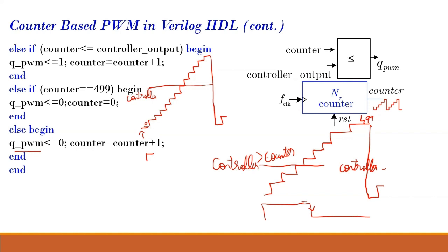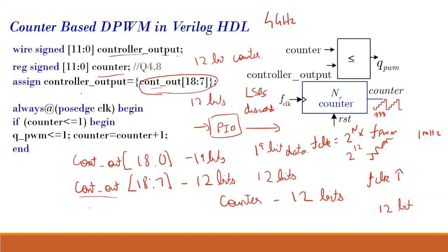Okay, then at the next clock, that is why this always block is there. This block determines that only at the rising edge of my clock will I go into this block of code and check. So when the positive edge of the clock has come, you go into this begin. Once it goes into this begin, it first checks this if condition.